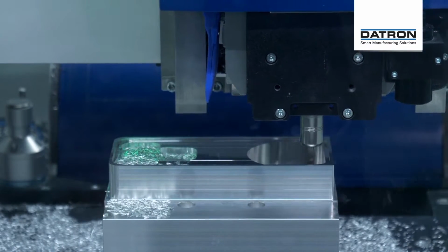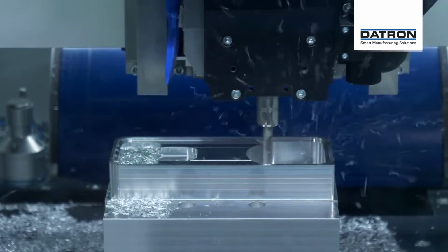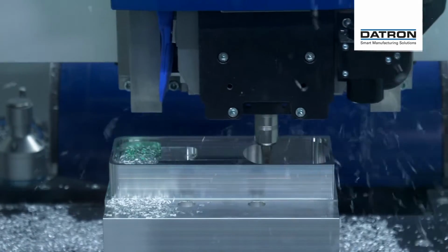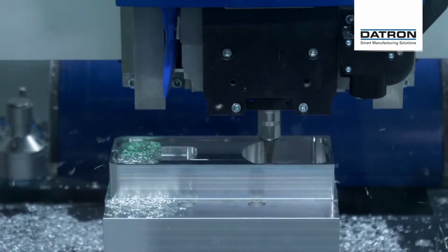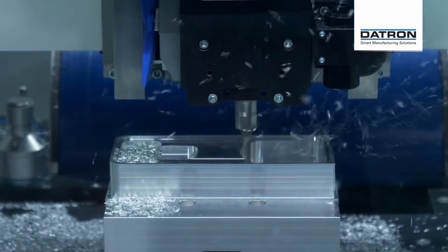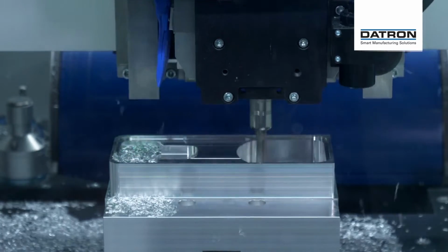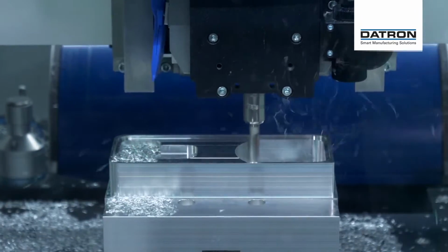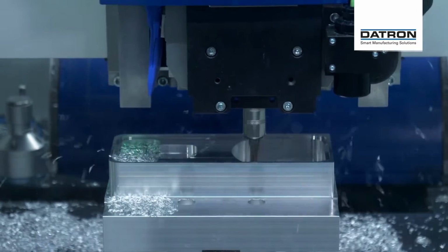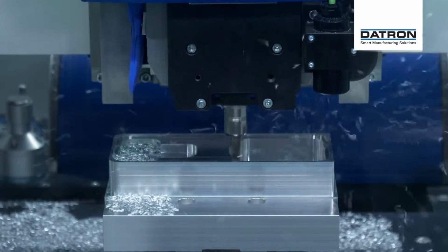Furthermore, we can connect more or different programs, different parts that we want to do in one setup. So we have this housing which we are currently doing, but we could also do something on the vacuum and just let it run after this housing. So not in parallel, but one job after another without manually changing the program which is loaded in the machine's software. So we can have multiple programs. We have a program management, we have an origin management, so different 0 points are possible.